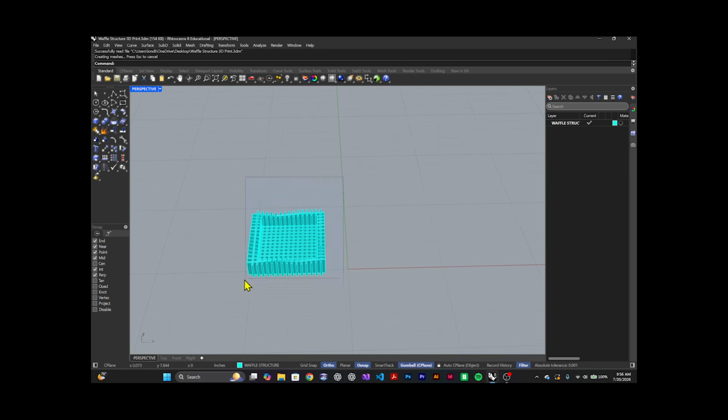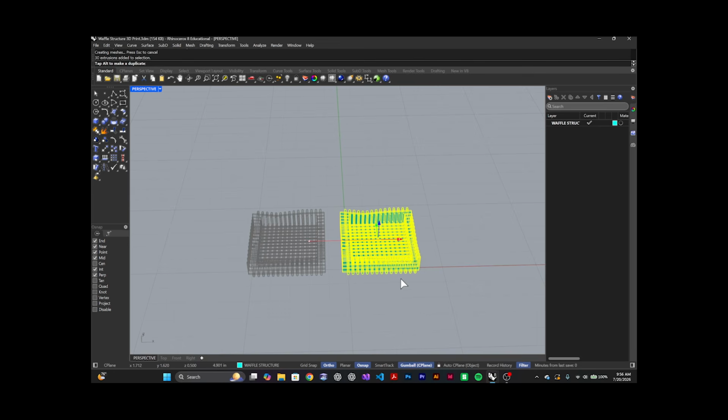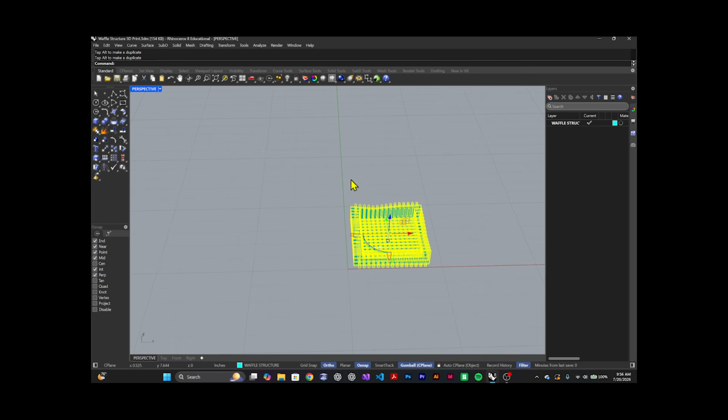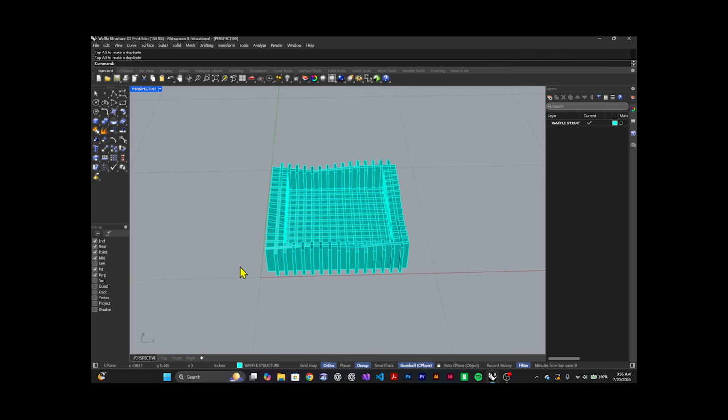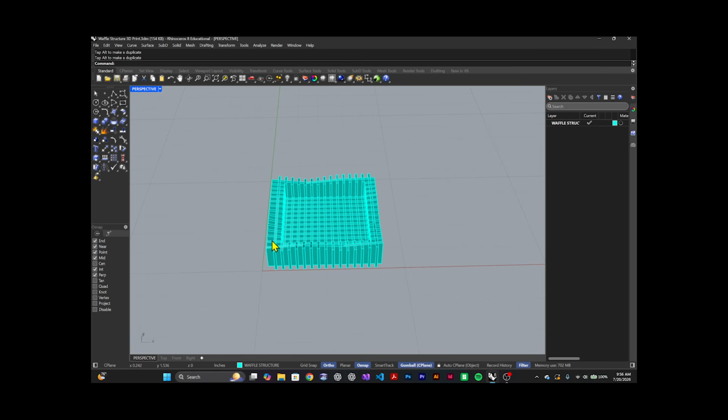and then you can move this closer to the origin point, which is the intersection of the y-axis and the x-axis. Wherever they intersect, that's the origin point. Now, one thing to note, and this is very important, guys: the 3D printer works in millimeters, and right now, if you noticed, we're working in inches. So if we were to save this file for 3D printing,